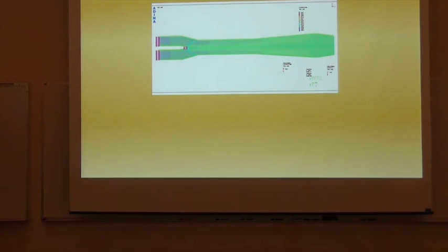From the results we got, temperature can also tell us a lot about the quality of mixing of air and gas. So we can see as we go on, it's very important that the mixture is really good here, because here's a lighter and the flame comes out of this spot. And we can see that the temperature is getting more and more uniform towards the end.